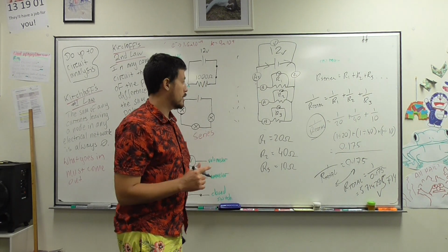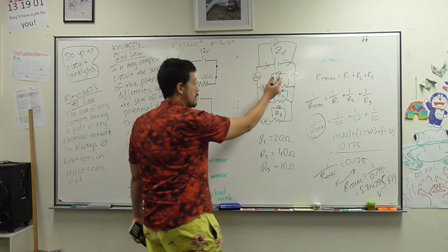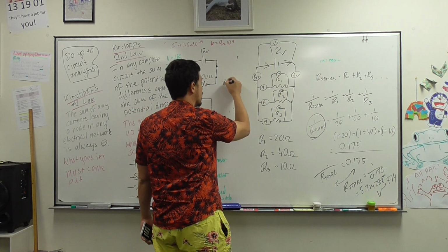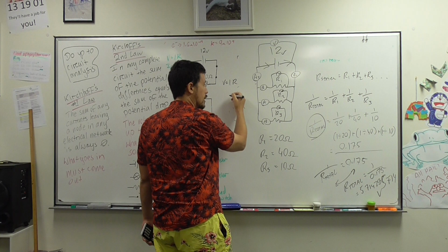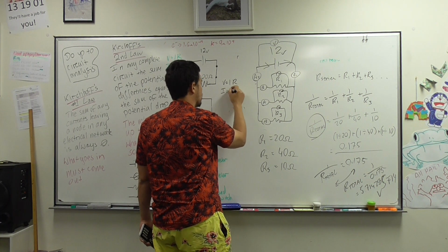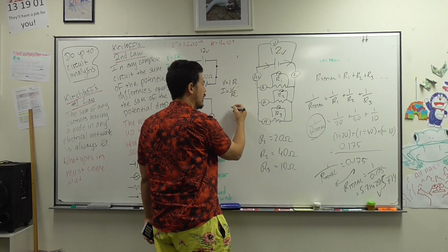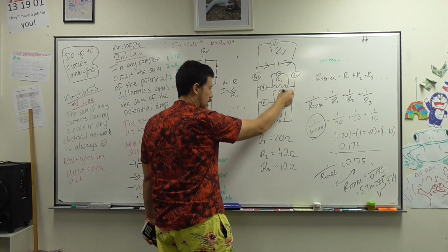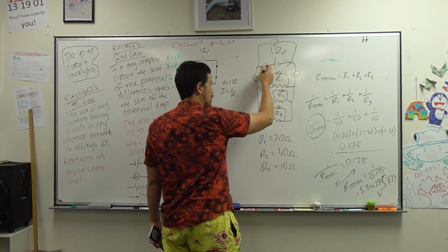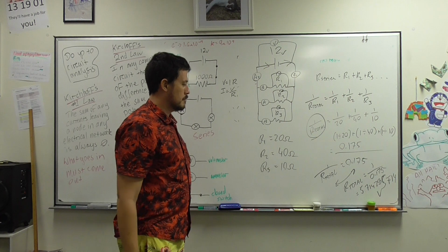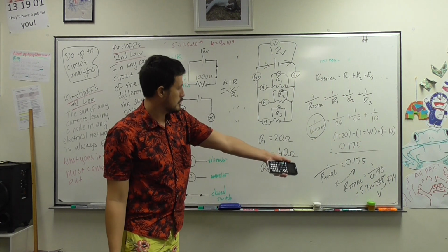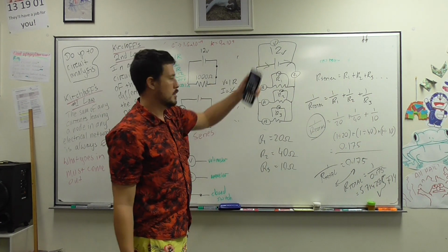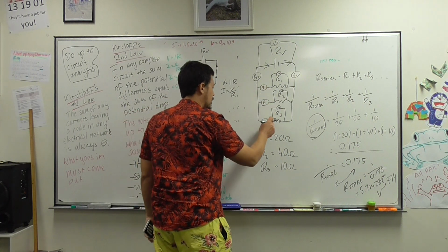So we can work that out. You can apply Ohm's law here. V equals IR. Then how do you work out the current? I equals V on R. Well, you have I. Do you? No, we don't, because the current's going to split. We know the current here and here, because we've got the total resistance and we've got the volts. But we don't know the current here, here and here.